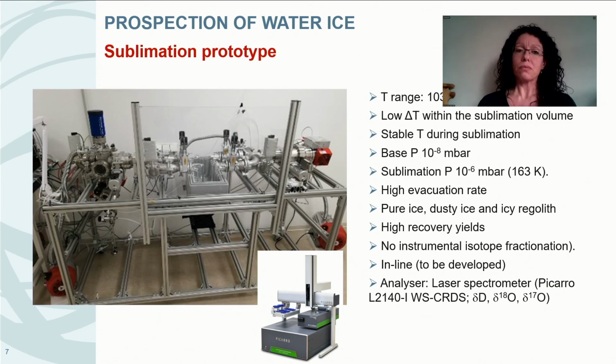The specifications for this first version are a temperature range of 103 to 473 kelvins, a base pressure of 10 to the minus 8 millibars, sublimation pressure of 10 to the minus 7 millibars at around 163 kelvins, and a high evacuation rate.